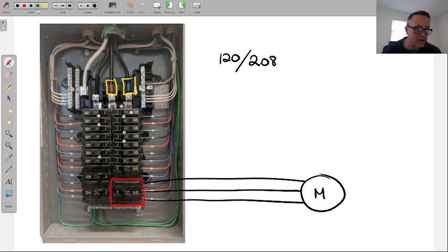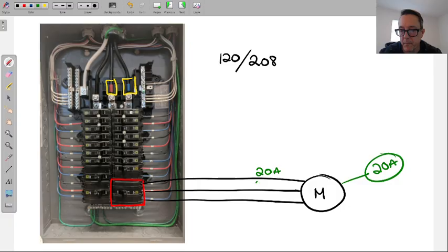So now let's think about it, and here's where we'll wrap things up. A few minutes, give me just a little bit more of your time. This is a load motor. Let's say the load on this motor is 20 amps. When it turns on, it generates 20 amps. This is what that means. It means if you measure A phase, 20 amps. If you measure B phase, 20. And C phase, 20. First of all, yes, 100% of the time, unless we're in some other physics world, it'll be even throughout all 3 phases.